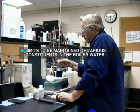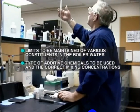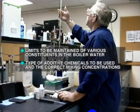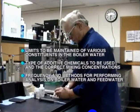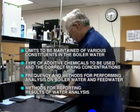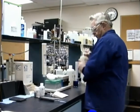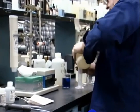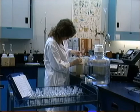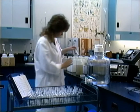Now, this will include the limits to be maintained of various constituents in boiler water, the type of additive chemicals to be used, and the correct mixing concentrations, the frequency and methods for performing analysis on boiler water and feedwater, the methods for reporting results of water analysis. Most large power plants are equipped with specialized personnel and lab equipment to perform boiler water analysis and control. In smaller industrial plants, the operator may be required to carry out certain tests with backup from a visiting specialist.